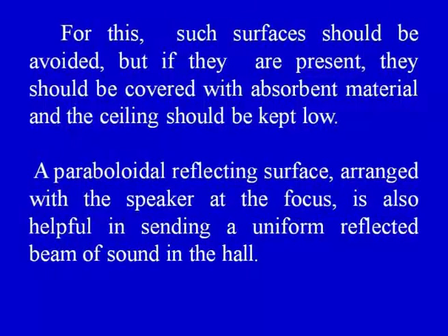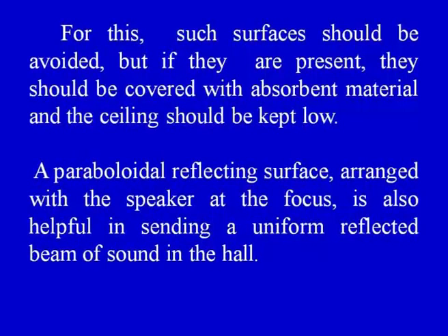For this, such surfaces should be avoided, but if they are present, they should be covered with absorbent material and the ceiling should be kept low. A paraboloidal reflecting surface arranged with the speaker at the focus is also helpful in sending a uniformly reflected beam of sound in the hall.